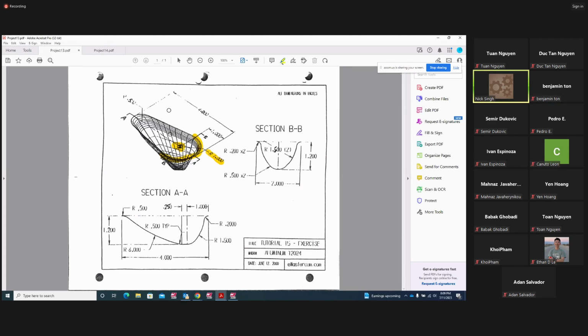And then we're going to create another arc over here that is radius 1/2 inch arc right here. Once we have those two arcs, we're going to create a tangent line right here to these two. So that's what we're going to do in the construction plane top.